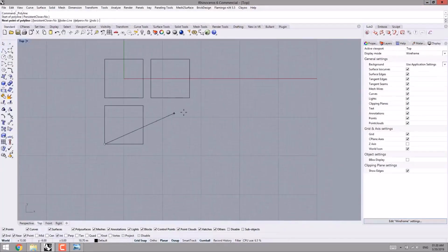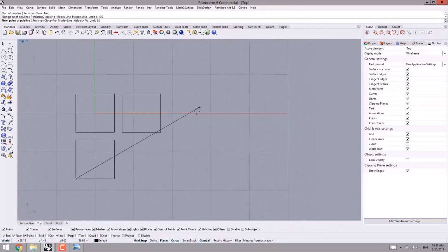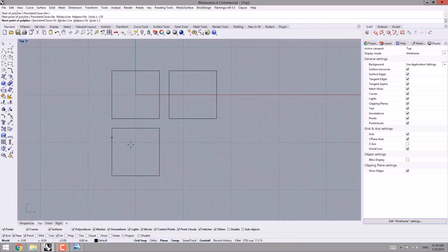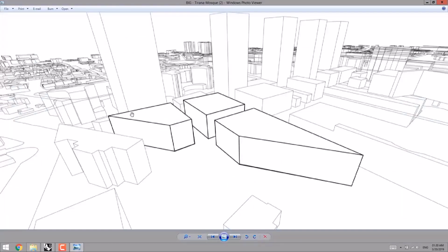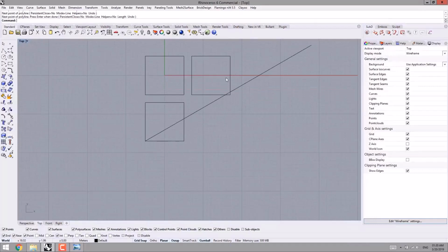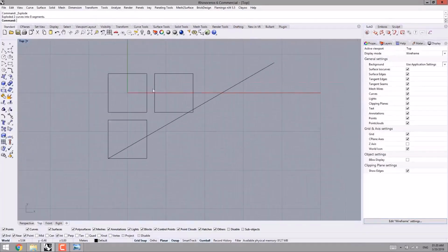I pick the polyline, and then the less than symbol 30. Enter. Here we got a 30 degrees line. As you can see, I have adjusted the angle as 30 degrees, but about the angle of the triangle I'm talking about here, which is 60. I extend the line till here, and then I select these two squares to explode them.